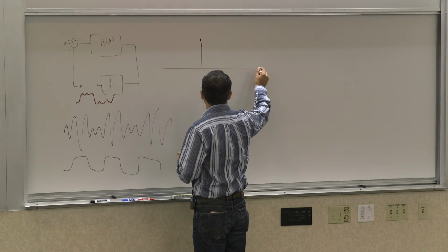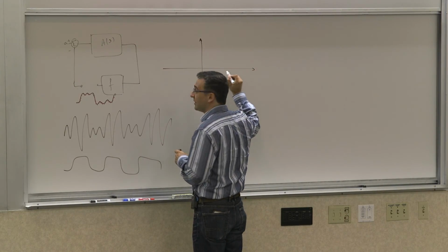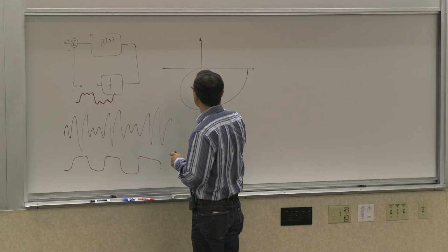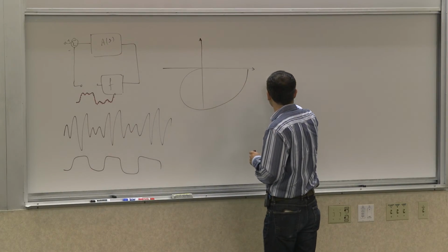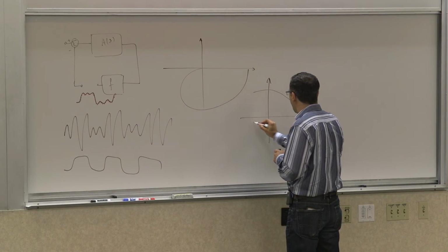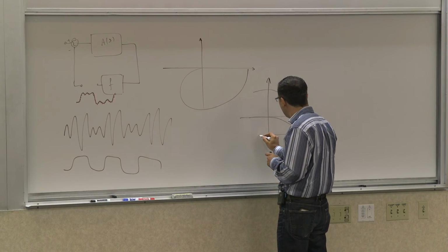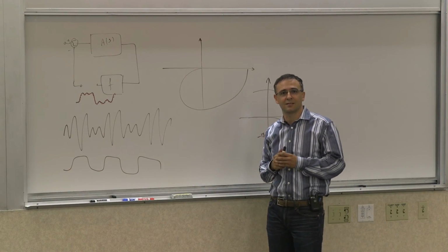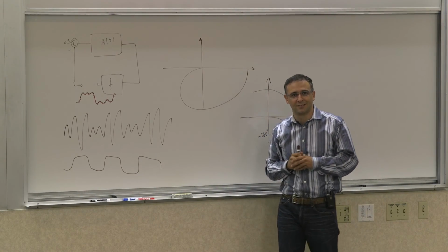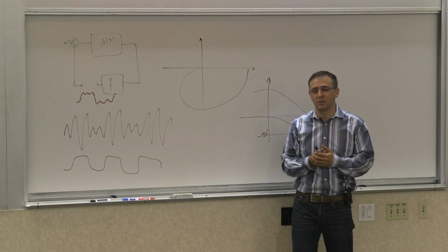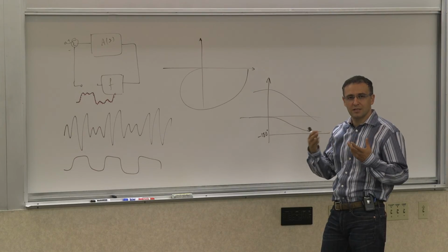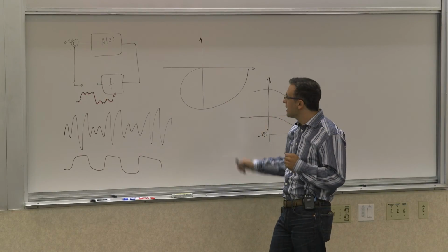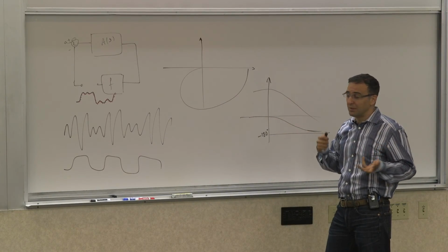In the Bode plot, the phase never reaches 180, and yet it oscillates with nonlinearity. There are examples of that in the literature, and you are going to be doing a couple of examples to see how these conditions are really just guidelines, unless you go to more accurate nonlinear guidelines. These examples can actually even be built in circuits.